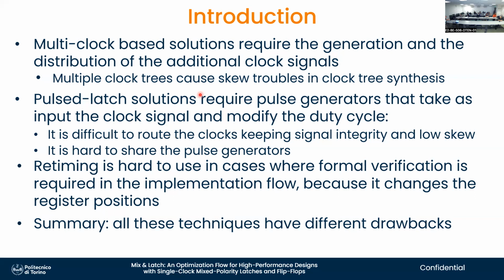Retiming is good because in terms of performance, it can improve significantly, as we will see near the end of this presentation, the performance of a circuit much beyond what a human designer can do. Not because humans are stupid, but because they cannot keep track of billions of flip-flops. It's only a computer that can manage the position of these billions of flip-flops.